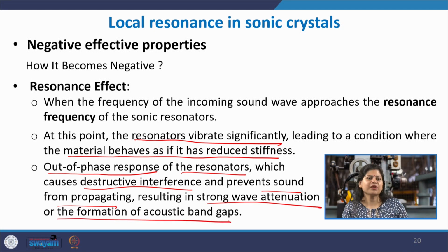So, the concept of resonance was already introduced in the previous lectures, that when a sound wave is incident on some structure and the structure attains resonance, it leads to attenuation at that resonance frequency.